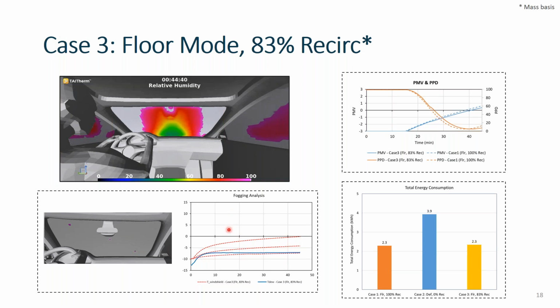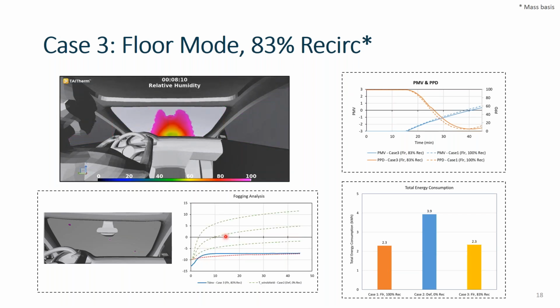Okay, so on this next plot, to help guide us to case 4, I've kept this same bottom line, our bottom point for fogging on the windshield. But now I've plotted these 3 additional temperatures. These are the glass windshield interior temperatures, these 3 points, for our defrost case from case 2. You can see our glass temperatures are significantly higher for our defrost case, as we saw before.